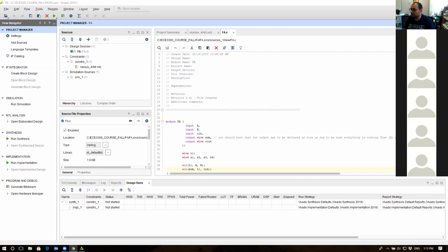So the critical path issue can be helped with the carry look ahead generator with an adder to improve the critical path. Yes, yes, Mario. Because by the way, the full adder has two different designs, and we're going to talk about this. One is called RCA, ripple carry adder, and the other one is called what? Carry look ahead adder. Okay. Anyway, back to the point.